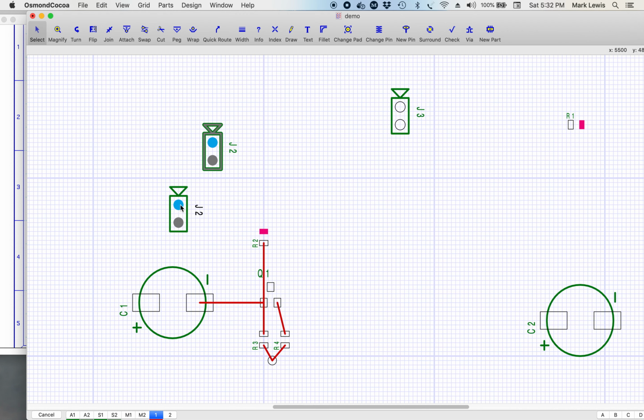This is going to be our incoming power for this. I just put it up here for this amplifier. This would be what we connect our 15 volts. I can have it go straight there, but let's say something was in the way and I want to route that around it. I go to quick route and I can physically click on that signal and I can drag it wherever I want to go.